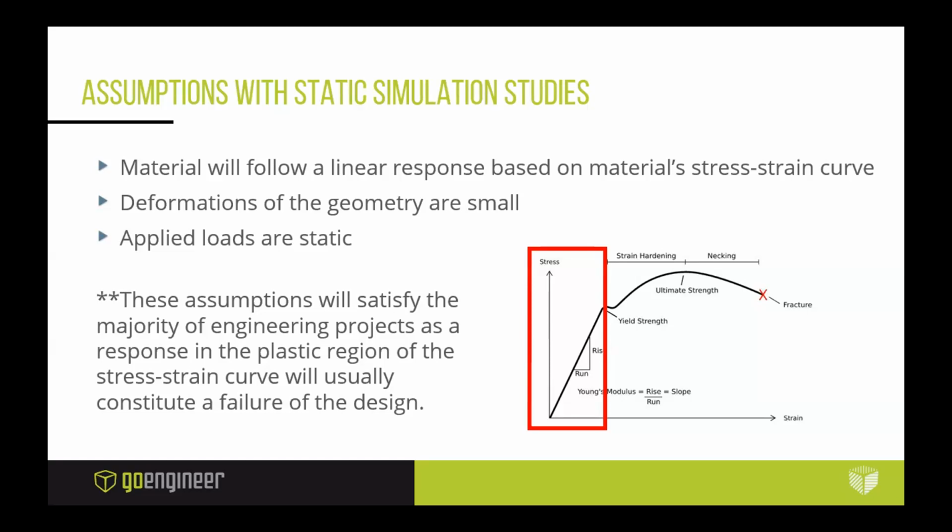So we cannot change a force as a function of time in this case. There is no time variable. If we needed this behavior, we have you covered with a dynamic study. We can do that. To kind of push the limits of the tool, you can run a dynamic study if you can assume that the inertial forces are negligible.